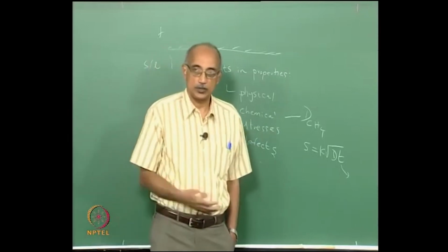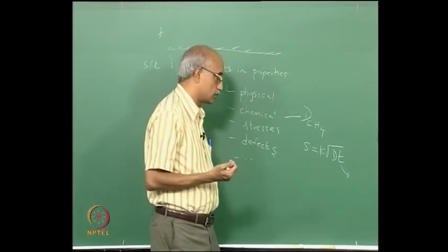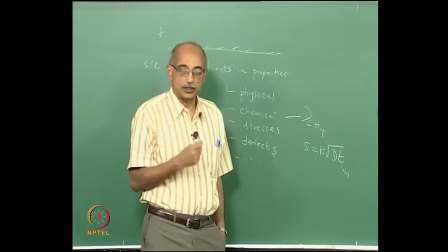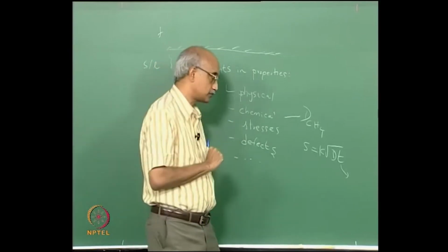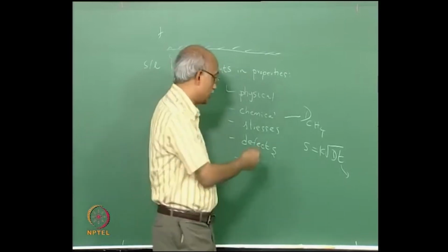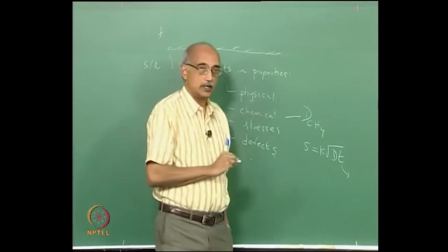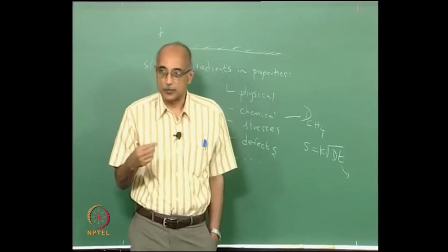You take the diffusivity of the species, multiply it by the time, and take the square root. That basically gives you the time dependence of the depth of penetration by this reactive gas. So essentially you can not only introduce a chemical gradient, you can actually control it when you are doing it as part of a manufacturing process.